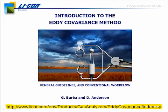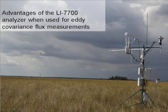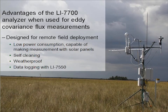We're going to shift gears now and talk a little bit more about the LI-7700 analyzer itself and some of the advantages that we see for using this instrument for Eddy Covariance fluxes. As I've mentioned throughout the talk, this instrument was really designed for remote field deployment, and that's important because to make these measurements, we really need to be in areas where methane fluxes are interesting. Those areas tend to have limited access to infrastructure. So low power consumption and being capable of making the full complete measurement with solar panels is really important to an instrument for these kinds of measurements.